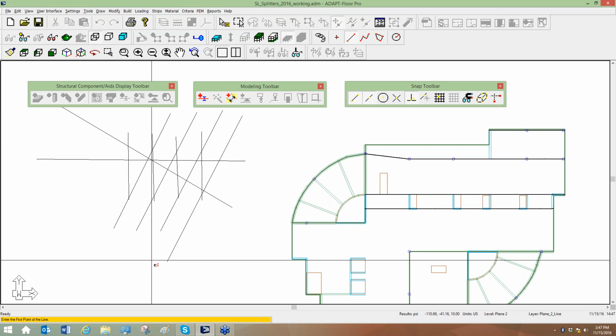And that goes against, I think, the traditional way you would design post-tensioning in a non-3D environment. You typically say, for this direction, we're assuming the banded tendons provide 100% contribution to the frame lines in one direction, and in the other direction, we assume that the distributed tendons provide contribution.